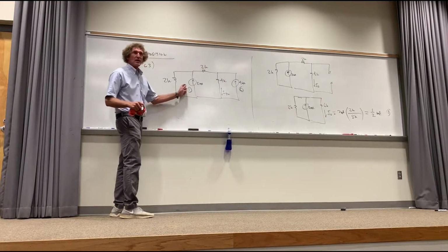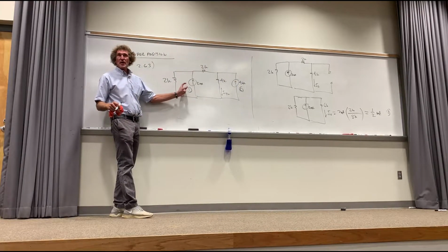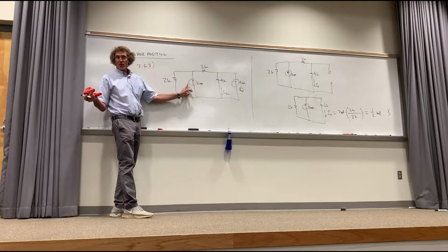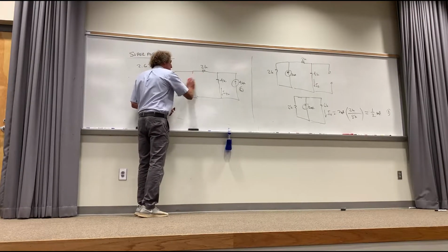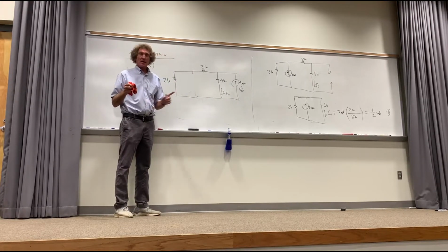I'm going to do it right here. Can you all see this? So now I turn off this source, right? What does it become? Open. Open circuit, right? It's a current source. Open circuit, you just erase it. Doesn't exist, right? Now I want to find that current. Correct, class? I want you to follow me on this one. Y'all see what I'm doing?